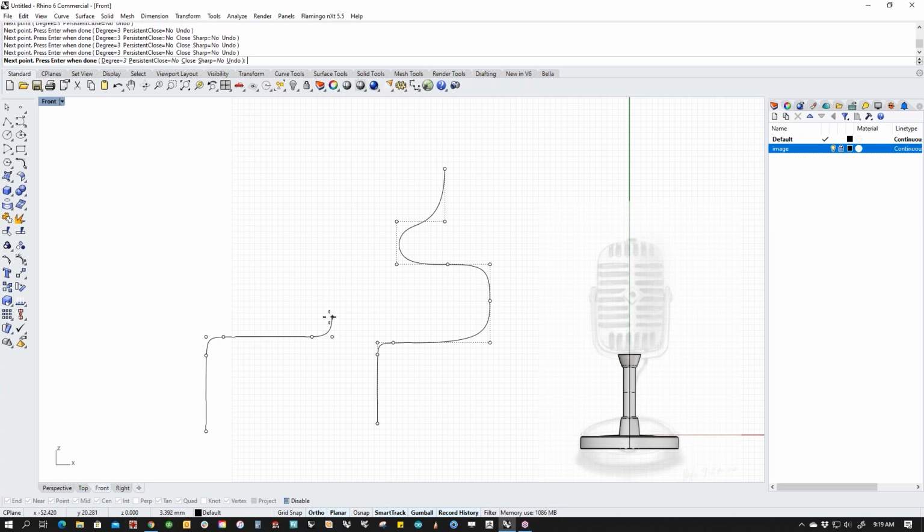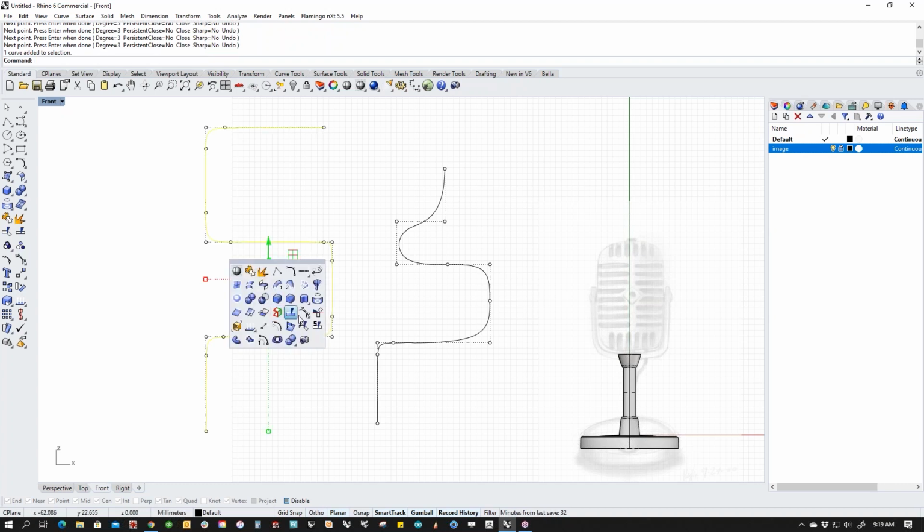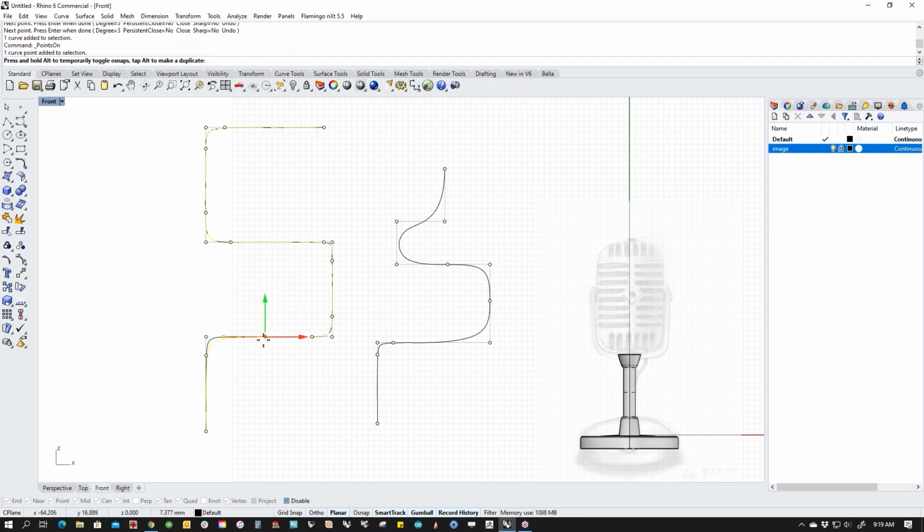But if I want to do it a little bit more accurately, I would say 1, 2, 3, come over here, 1, 2, 3, come up here, 1, 2, 3, and then lead it out. And now the way that this is set up, I can control this corner independently from this corner. So that's a case where you would want each corner to have 3 points individually. In this case, if you want to soften it up, you can share a point. Maybe I want to place that right in the middle and know that these two corners are going to blend fairly similarly.